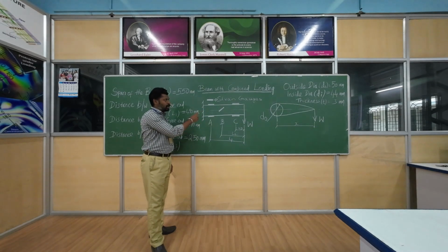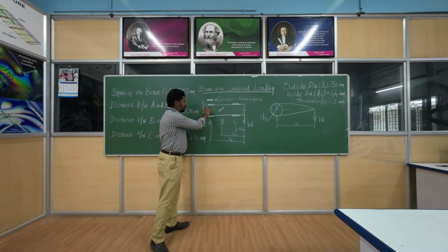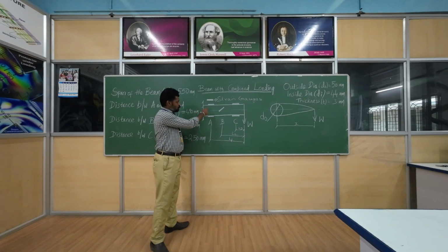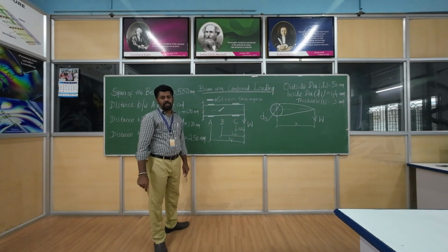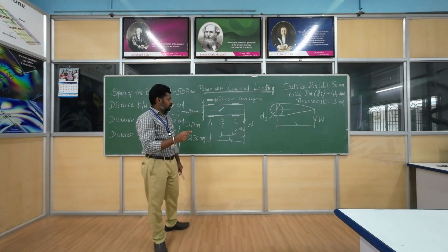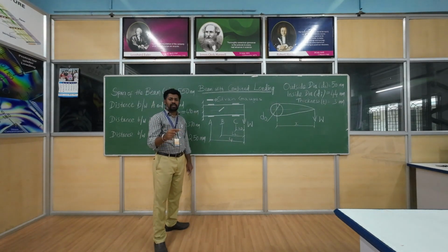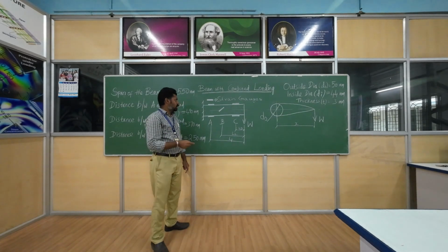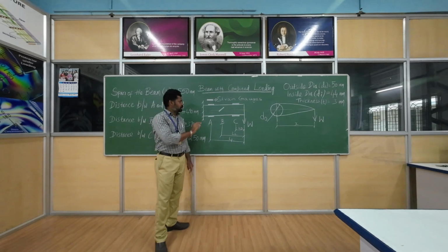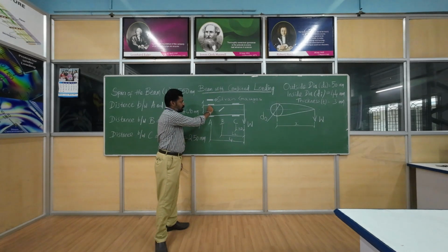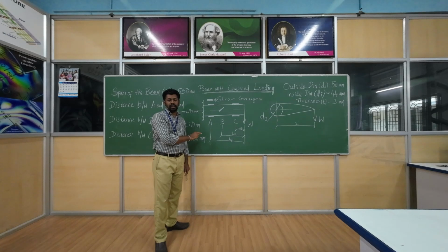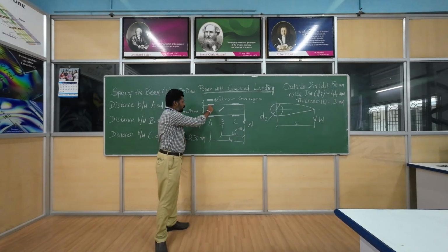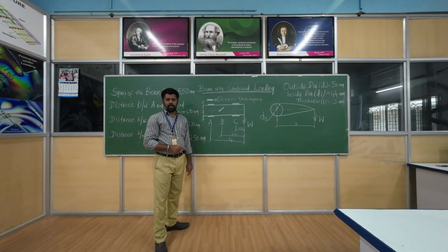Again, in order to get the strain, we have mounted strain gauge on the top of that beam and on the bottom of the beam. By doing so, we will get the half-bridge circuit. The strain gauge details we will discuss in the later sessions. As of now, you can keep in mind that we are going to use 2 strain gauges to get the strain at the section A. By using 2 strain gauges, we will be using half-bridge circuit.